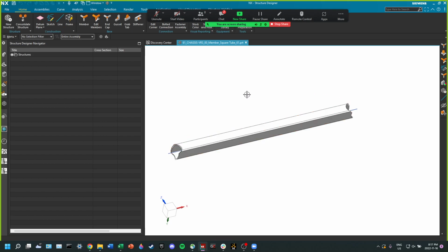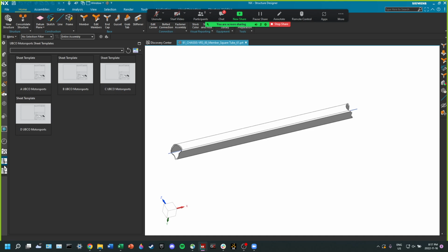Okay, it's here. Once you have your two little tabs on the side, and you have your final CAD done for your part, the process for making a drawing is this. For the non-master drawing template, select whatever sized drawing you want to do.